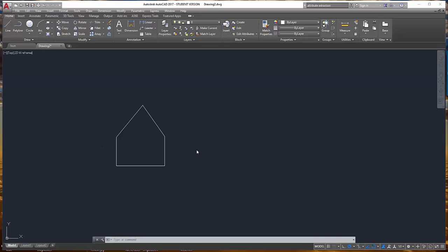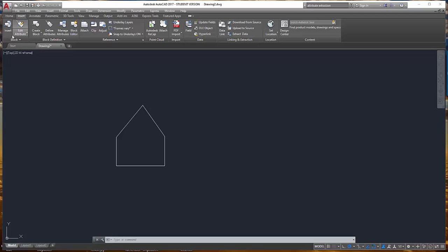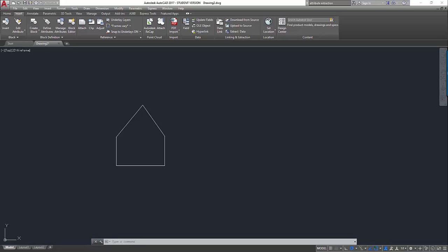And so a W block, which is known as a right block, can be found under the Insert tab. So the Insert tab up at the top provides us all the information in the area that we're going to be focusing on primarily today. So to begin, we're going to show you how to create a W block without an attribute. Then we're going to create another block with an attribute. And then we're going to show you how to bring these blocks into a brand new drawing. Not into the drawing that it was created in, but into a brand new different drawing.